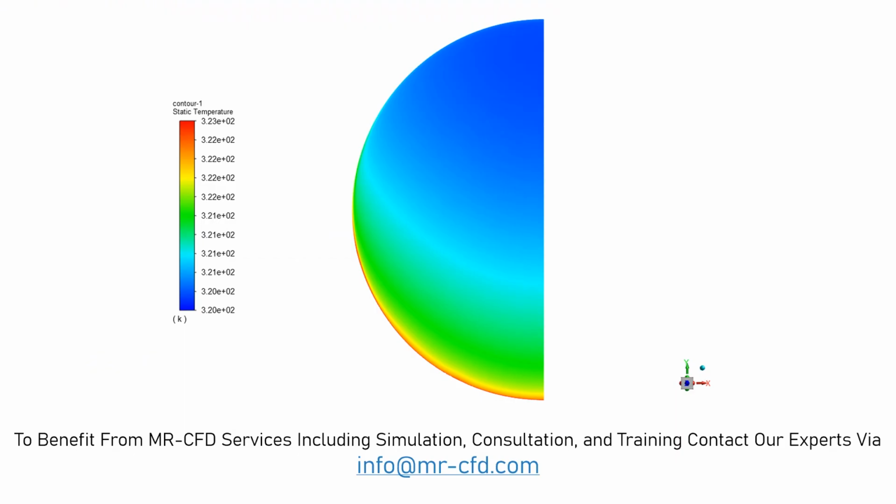In this slide, you can see the temperature contour on the outlet boundary. You can easily see the temperature changes on the lower section of the outer wall where we had the higher heat flux applied.